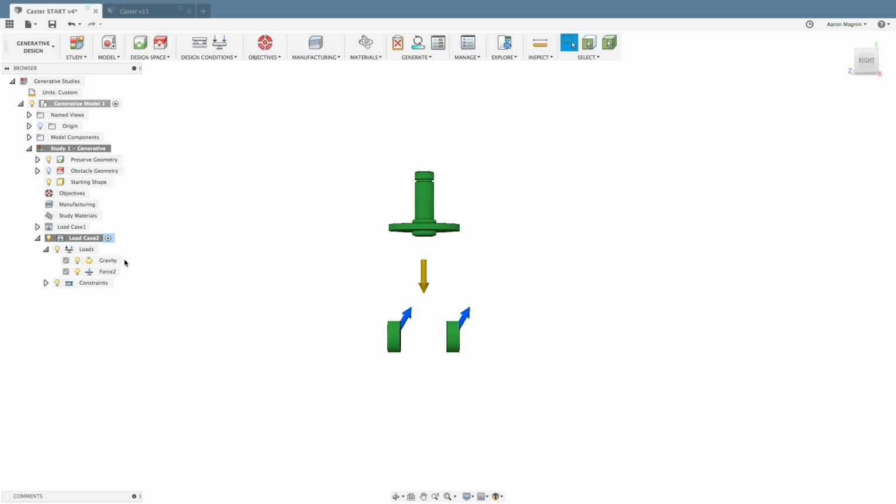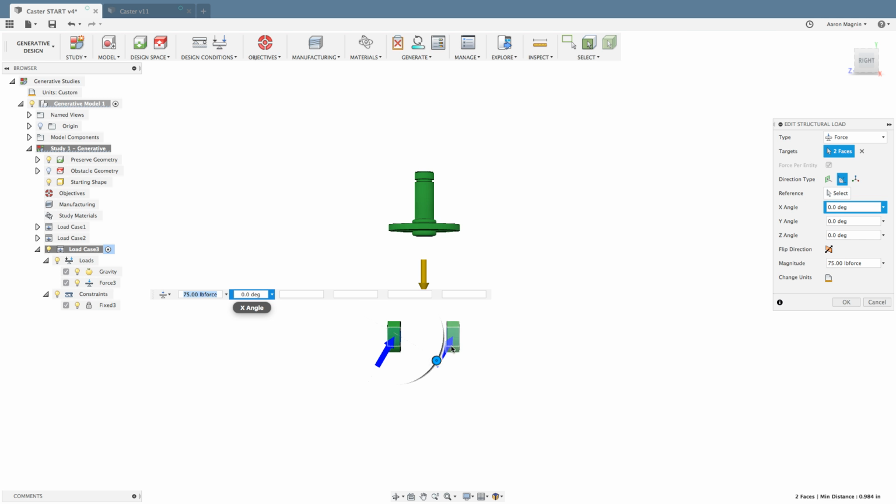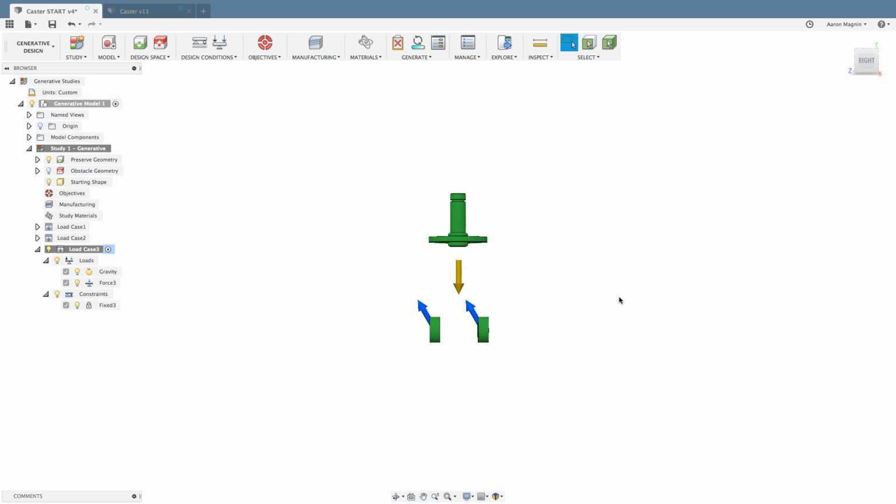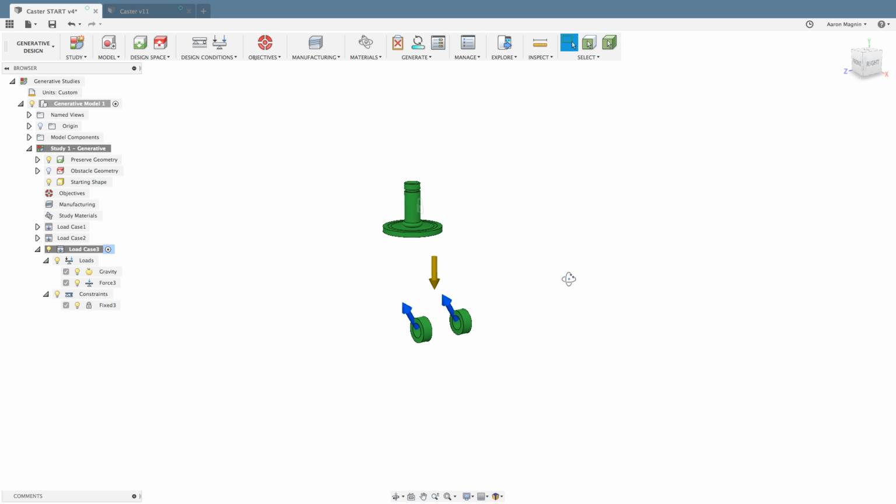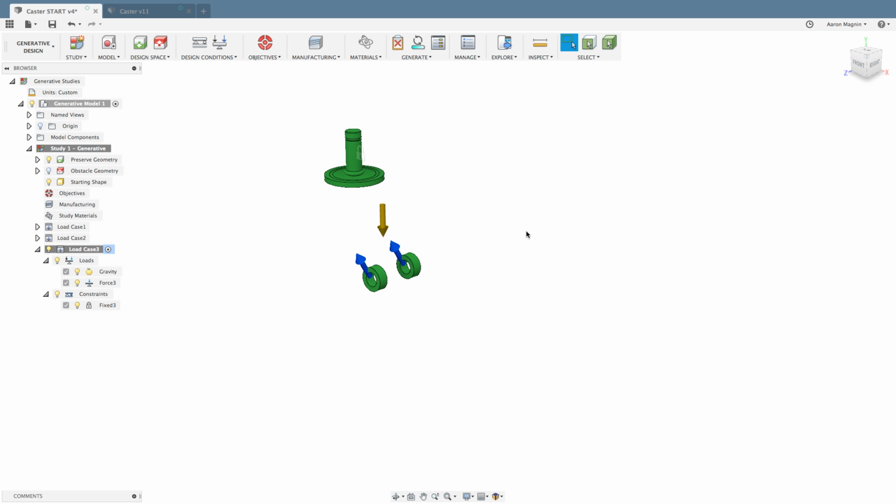So that's always nice. Let's go ahead and clone this load case once again. And again, by cloning it, it enables us to avoid having to create a new constraint. It also enables me to just reuse that force with the new magnitude and go the opposite direction. So we'll go ahead and go -60 just to flip it up. And as we're dragging, it'll want to snap to those rounded values. And just like that, we've created 3 different load cases. Now we can move on to